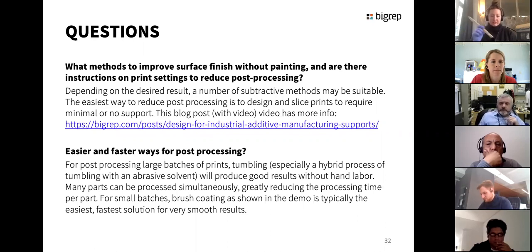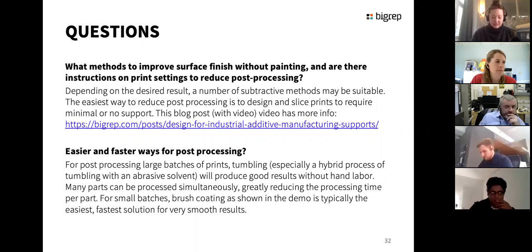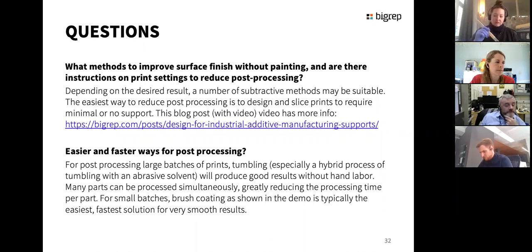So I would suggest that. Otherwise, there's not so much you can do if you really need to heat the part. It depends on the temperature resistance of that specific print material. So go for the carbon fibers and the high temp materials, and that should greatly reduce it. I would avoid using HT and Pro HT. That's going to have a little bit more tendency to warp.